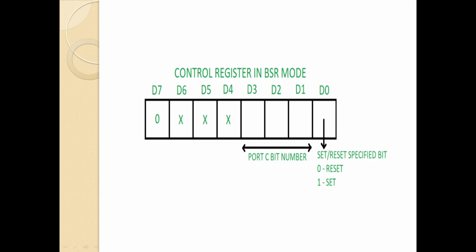Here, in the previous functioning of the blocks, we were talking about the control register. The control register is provided by the CPU of the processor. So whenever the 8255 is operating in the BSR mode, this 8-bit control register is provided to the 8255 chip.